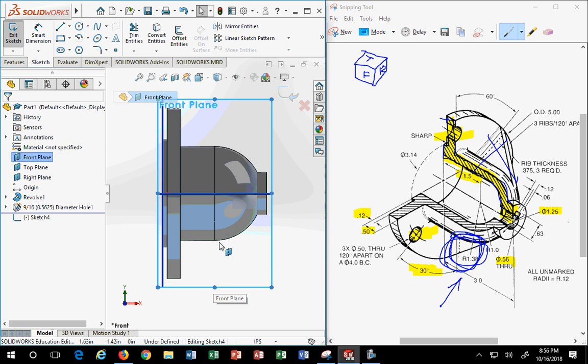Now, a few things to know. When I want to create anything on a round surface, I can't use my traditional convert entities approach that I would tell you to use normally. Instead, I would have you pick intersection curve. Anytime you deal with something that's actually round and you want to slice through it like an apple, you have to use intersection curve. You can't use convert entities.